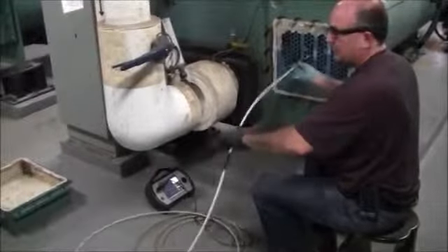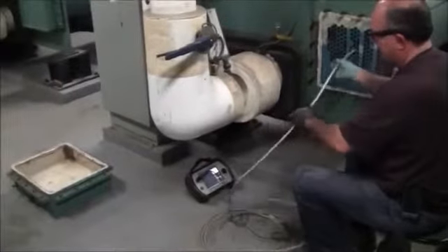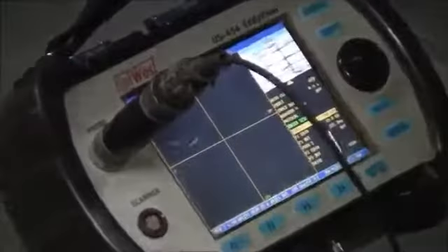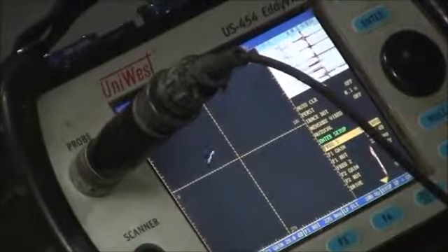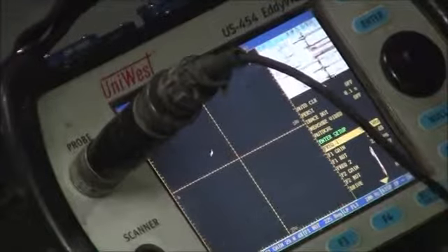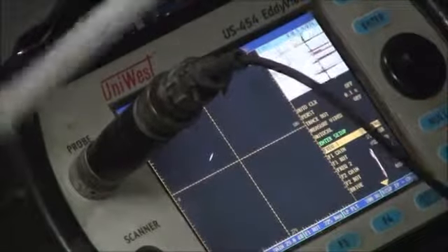So anyways, this is eddy current testing for the machine. And he's looking at that dot to determine the thickness of the tube, and he can determine the thousandths of an inch of how thick the tube is. And also, as he goes through the tube supports, he can see the pattern that is being displayed on his display there.